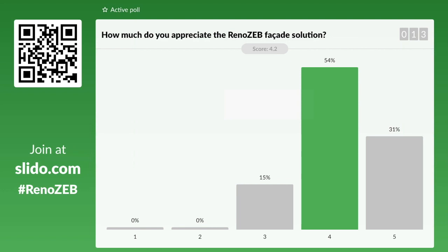But it's obviously considered. And the main issue, just to mention to you, because it's a focus, we need to pay attention to when we, in general, retrofit a building, but also obviously use this type of product, is related to the load bearing structure of the building. This is a lightweight element we install on the existing building. So the load bearing capacity of the existing building needs to be able to support also this lightweight component. And this is one element I'd like to catch your attention to because it's very relevant.